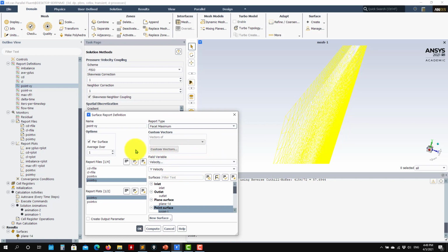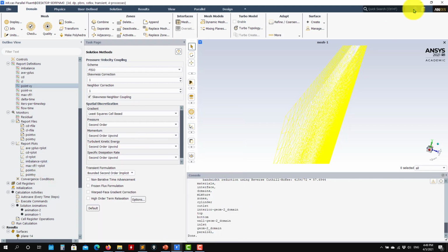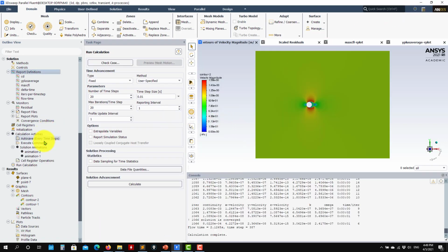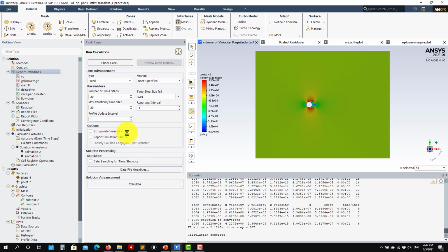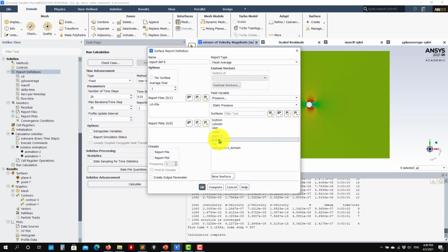So you can sample in whatever. You're putting all this information on all these points, saving that information. For instance, let me do it also as well. Let me create that monitor. If I go here, new, it will be surface, I will put phase average, it doesn't make a difference. I want to sample in this point, and I want to sample velocity, this Y component. I will call it 0.7 by and report to plot.